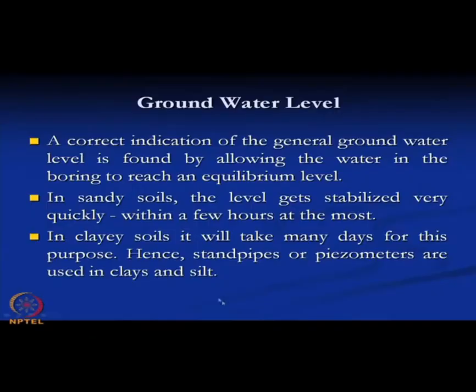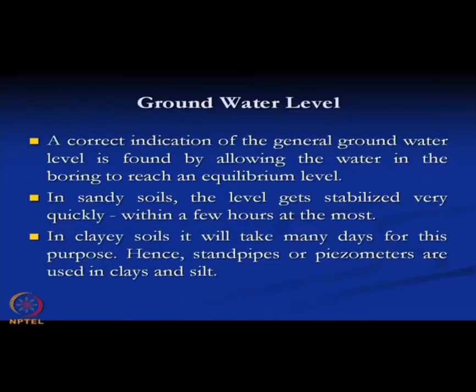Now, if the soil is sandy soil, the level gets stabilized very quickly, within a few hours at most. For the sandy soil, this water reaches an equilibrium condition very quickly, that means within an hour. But if it is a clay soil, then it may take a day, many days for this purpose. Hence, the standpipe or piezometer are used in clay and sand.